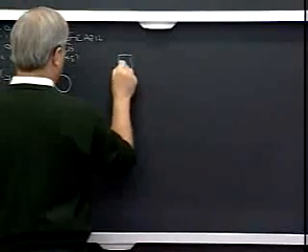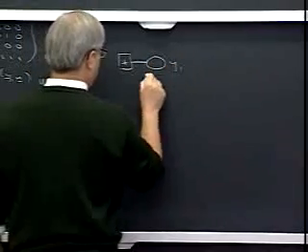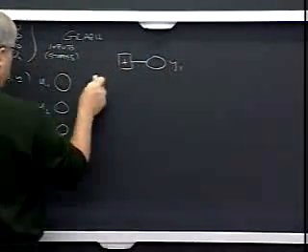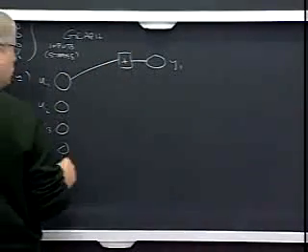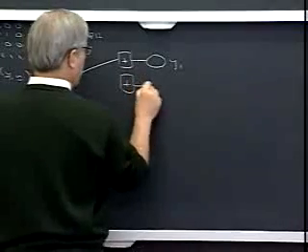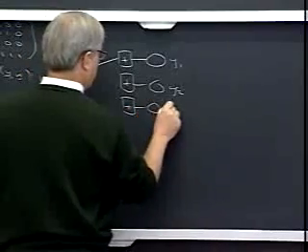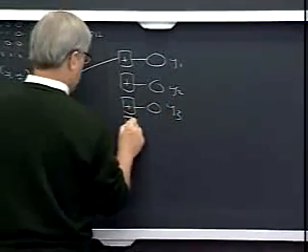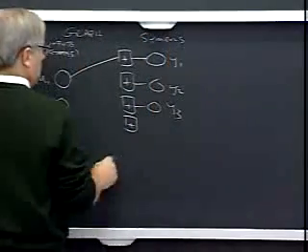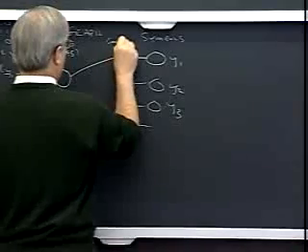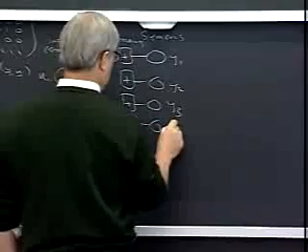And to get Y1, here's what we do. We're going to take Y1 and we're going to create a mod 2 sum of some of these inputs. In this case, it's just U1, so I could draw it as a straight through. But in general, I'm going to have to make a combination to get all of these. So I will have 8 symbols over here, code symbols. And again, some constraints that have to be satisfied. Equations, mod 2 sums.